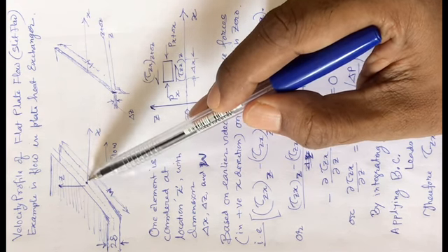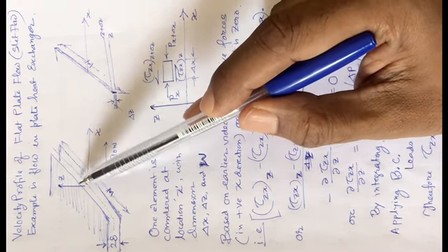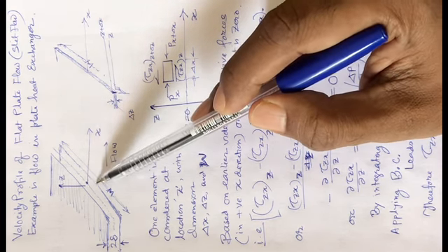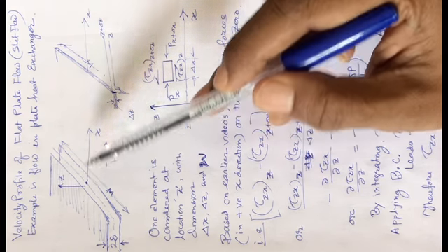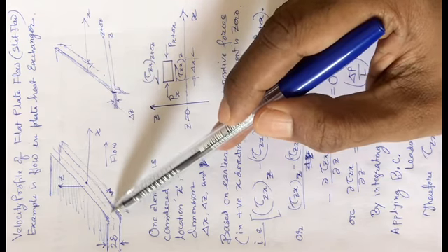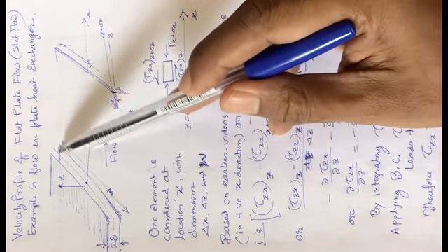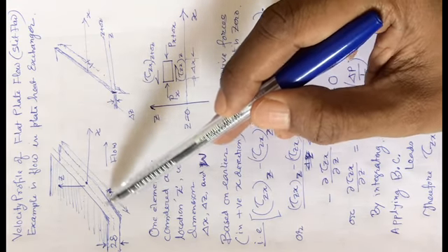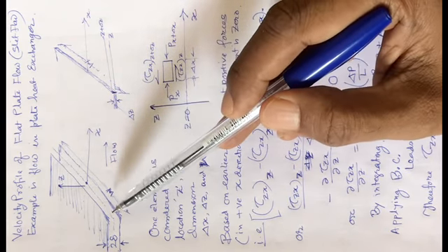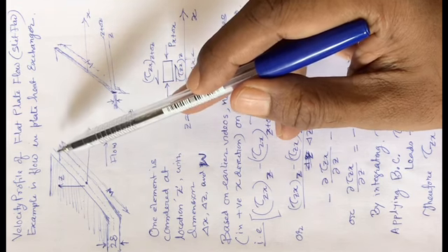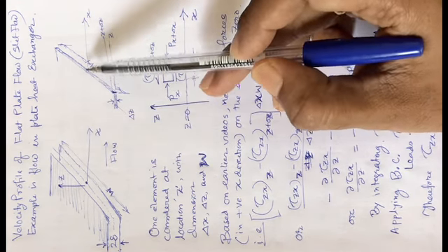Towards the top and towards the bottom the velocity decreases, and at the interface with the top plate and bottom plate the velocity becomes 0. So the midpoint is of concern. There is an axis passing through the midpoint and this central plane. Fluid moving at the central plane will be moving at the maximum speed.